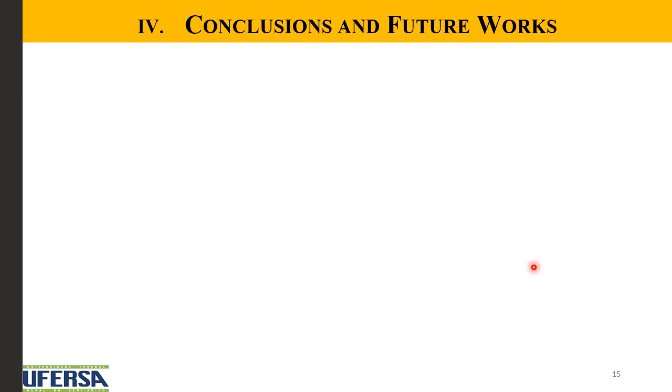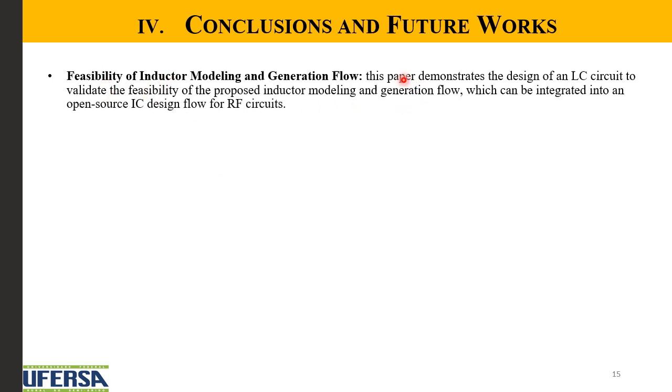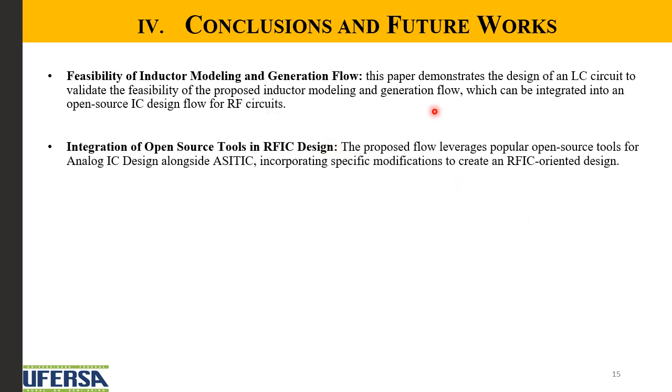And finally, about the conclusions and future works. This paper demonstrates the design of an LC circuit to validate the feasibility of the proposed inductor modeling and generation flow, which can be integrated into open source IC design flow for RF circuits. So this proposed flow leverages popular open source tools for analog IC, such as Xschem and Magic, alongside the ASITIC.